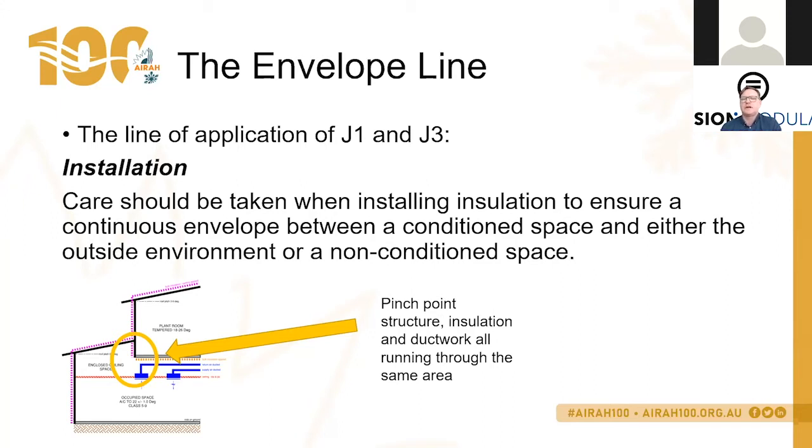So now we have a bit of an understanding of the building insulation location. We do know what we need to do with our ductwork insulation. All of our supply air ductwork in this instance will be considered to be in the conditioned space. But I'll also, through the case study notes, demonstrate a bit of comparison if it wasn't to be considered in the conditioned space and the ceiling plenum area was not part of the conditioned space, that it does have an impact on your duct sizing and reduces your options in regards to your duct design.